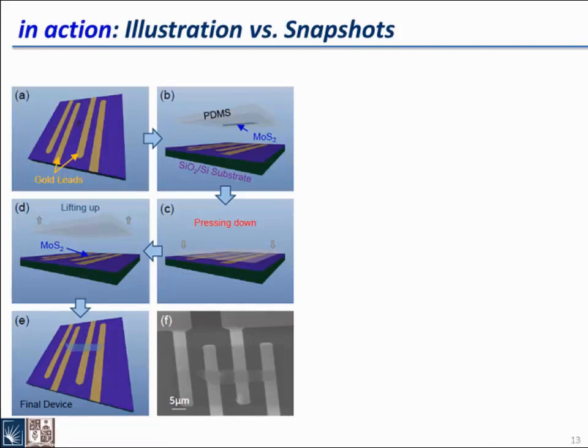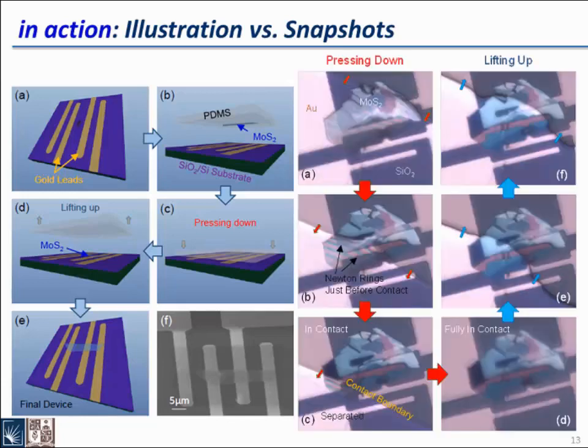So this series of cartoon images show you the process, you can follow A, B, C, D, E, and F. And this is a real-time recording. Then I put it into image showing the process. You can see the pressing down of the stamp. And this is the forefront of the stamp. So it's coming down. So there's a structure like this, air gap. Then you are expecting the Newton ring. Actually, the Newton ring is a signature to tell you that your process is going well.